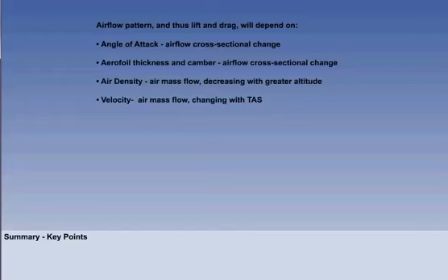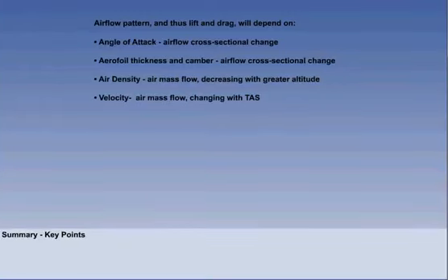To summarise the significant points of this lesson, we can start with the main things affecting airflow pattern, and consequently lift and drag. It will depend on angle of attack, airflow cross-sectional area change, aerofoil shape, that is, thickness and camber, air density, air mass flow decreasing with greater altitude, and velocity, air mass flow changing with TAS.